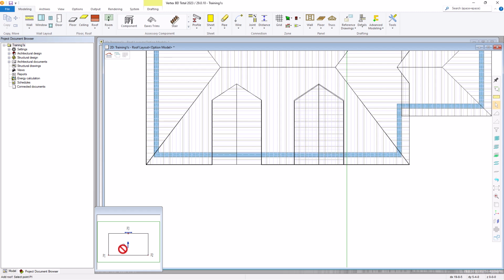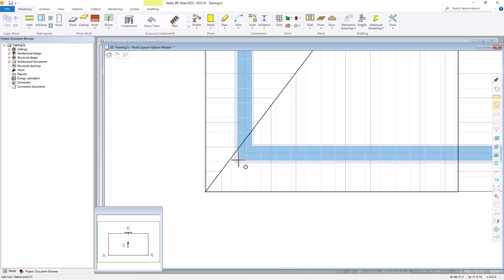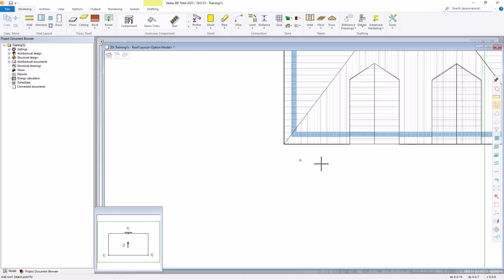As you can see, our selection diagram shows point 1 to the left, our next selection point, point 2, over to the right, and our third point is towards the middle top edge of the mono slope. And that's sloping up. Let's go ahead and we'll set that corner as a reference, so we'll hit Q off the framing corner. We'll type in 1 foot to the right. We'll come down, so that'll be a negative 3 feet. Hit return.